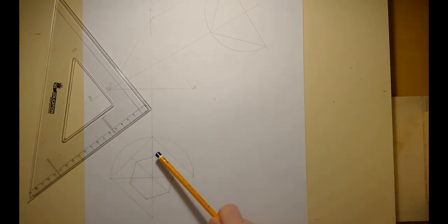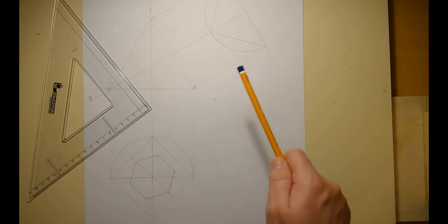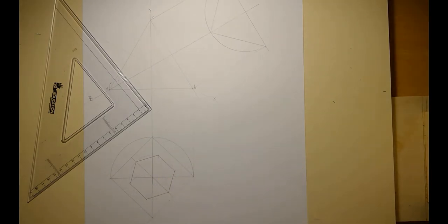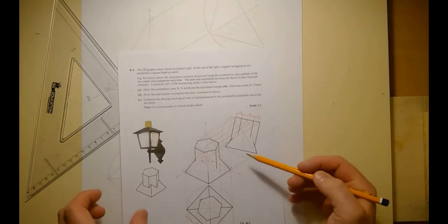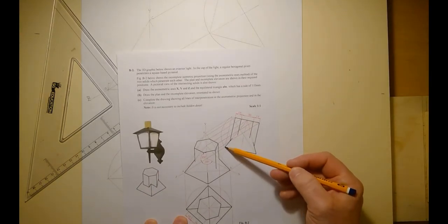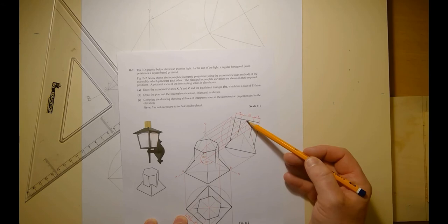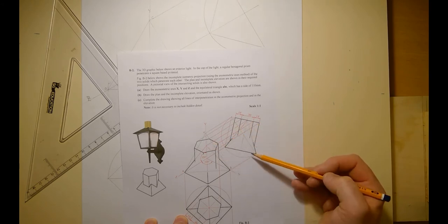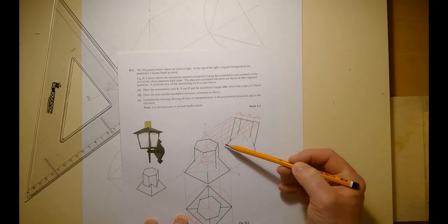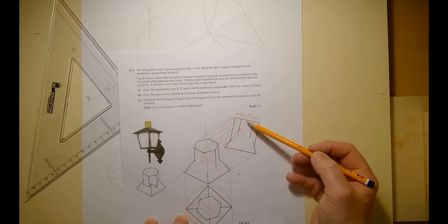Okay, so there's my hexagon drawn there in the middle of my plan, and I'm going to go up now to my elevation. And I need to look at what we're told for the elevation. You know that the pyramid basically starts here, goes up to a point here at the middle portion of that hexagonal prism, and it goes back down into this corner. So we have this line already. We want to locate the rest of it after that.